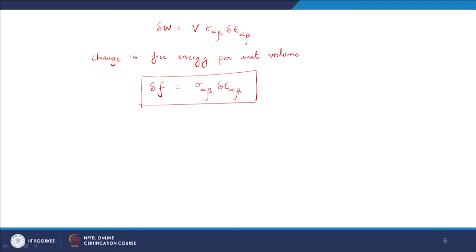When we are doing this, we have made basically couple of assumptions, and that become relevant for other materials. One is that we assume that the body force is negligible. That may not be true for all class of materials, and second we are looking at small deformations around the equilibrium that again will not be true for many class of materials. So, this is very limited relation that applies to materials such as the polymer networks we will discuss. This is not a general relation, so as to speak.